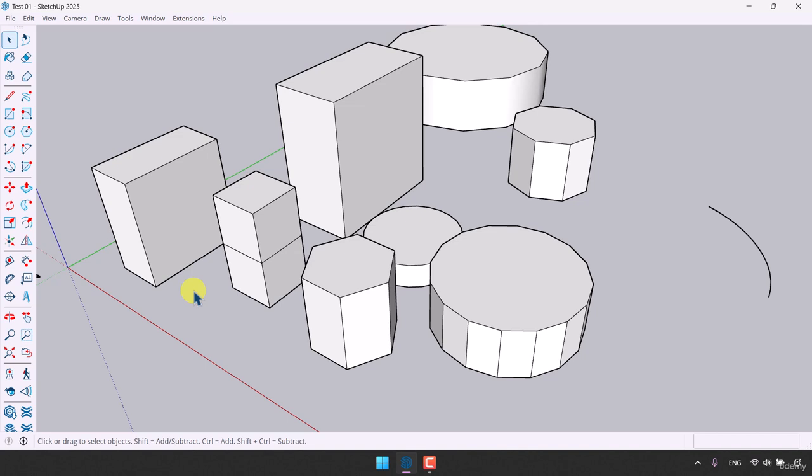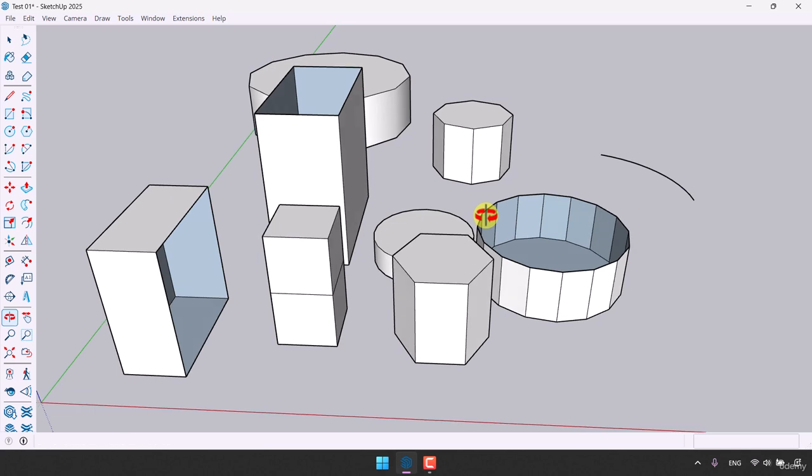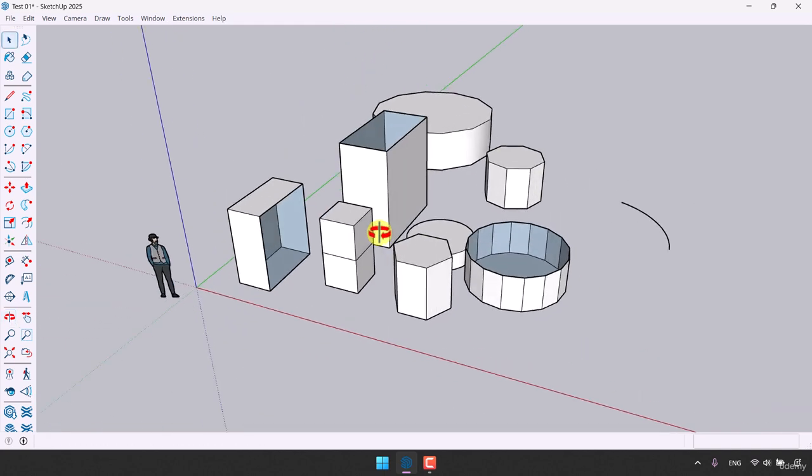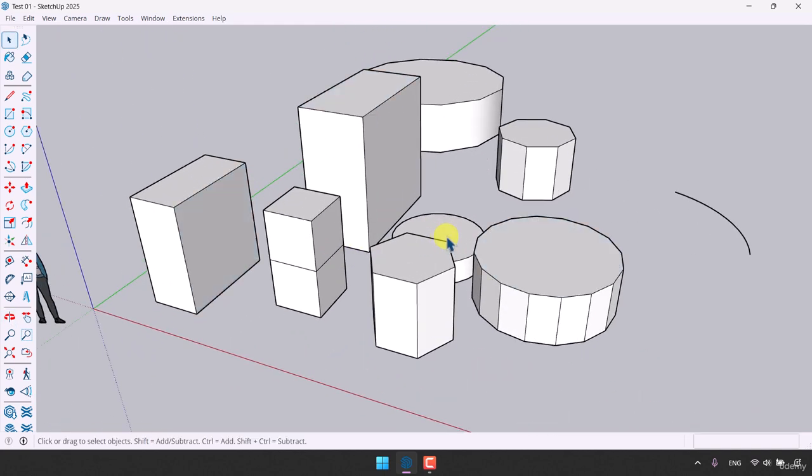And if I want to undo it and select them again, for example, hold Ctrl on my keyboard, left click on this face, on this one, on this face, on this one, on this one, like that. And if I want to deselect one of them, I only need to hold Shift and click on it, like that, and press Delete. As you can see, we can select or deselect the selected files or faces, very simple and easy. So another time we're going to review it.